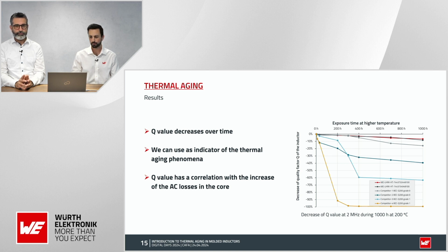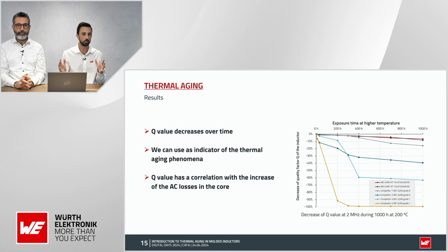And there is another thing that should be pointed out here. Does it mean that a part that has this very big degradation is broken? It's a good question. Is it broken? Will it stop working? And the answer is no. If we go to the extreme result of the thermal aging, where there is no insulation between the particles, we will have a part that still offers some inductance, but the AC losses will be super high.